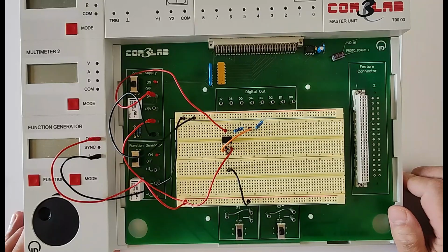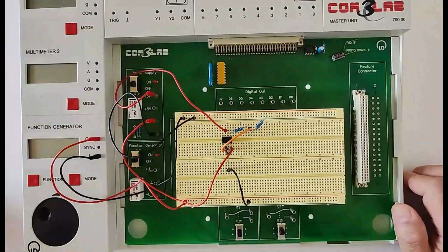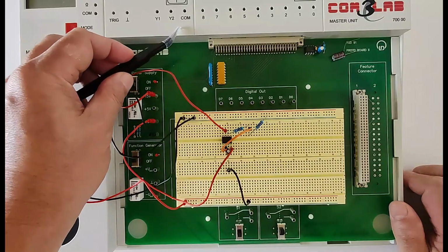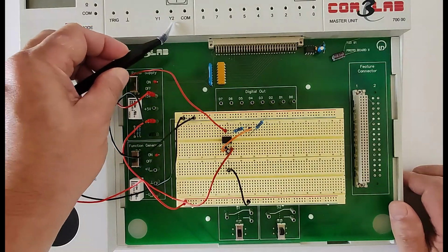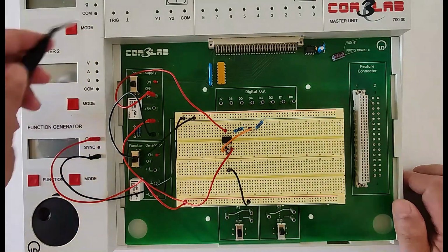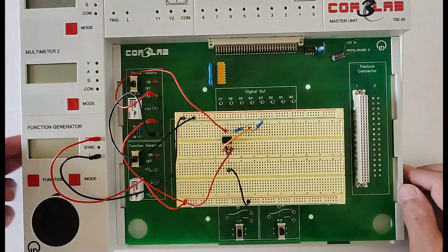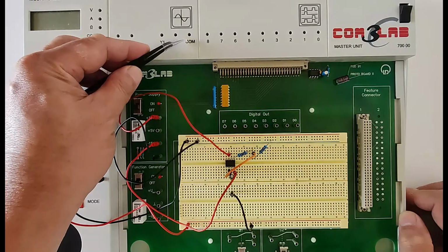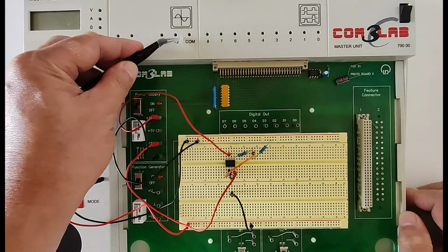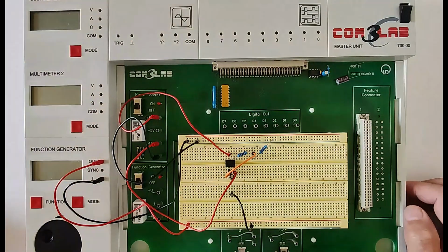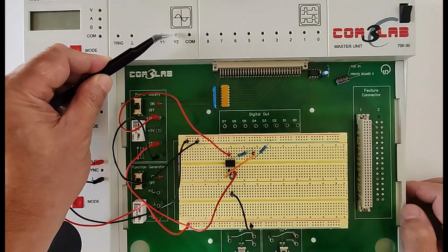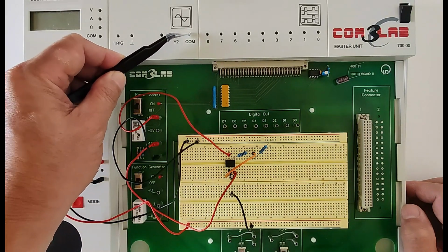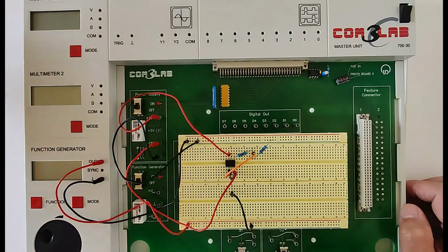Now, this more or less completes the connection of our circuit. It's completed now. Now, what's left is the connection from the oscilloscope. Let's connect the oscilloscope already. Just like in the previous video, I'm going to use both channels, Y1 and Y2, of the oscilloscope, and common. So I'm going to have connections on all three. Y1 will be used for the input, Y2 for the output, and of course the common or ground connection.